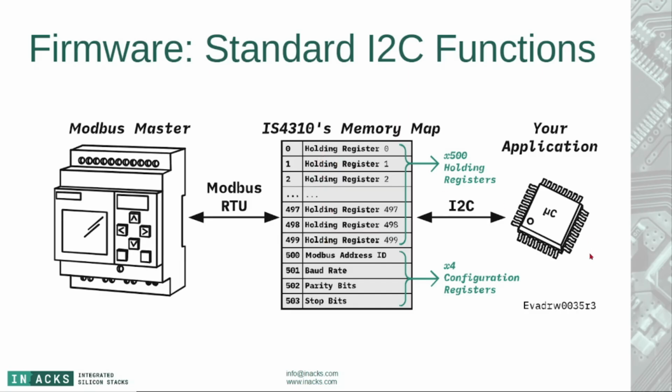If you are doing a temperature sensor, you read with your microcontroller the analog value, or you read anything from your sensor, and you process the data, and you store this data, let's say, in holding register 0.